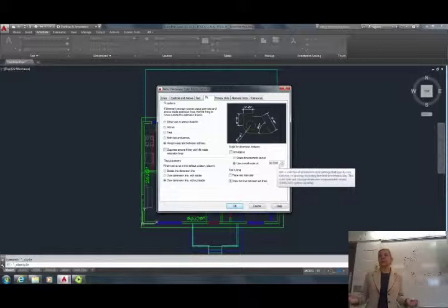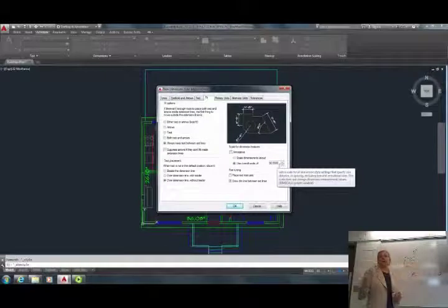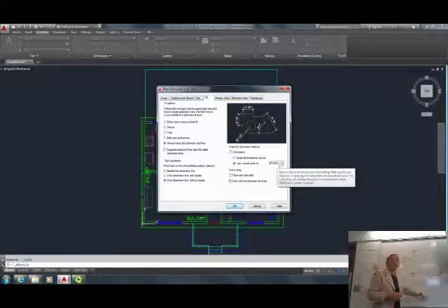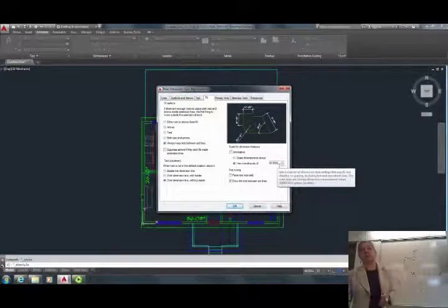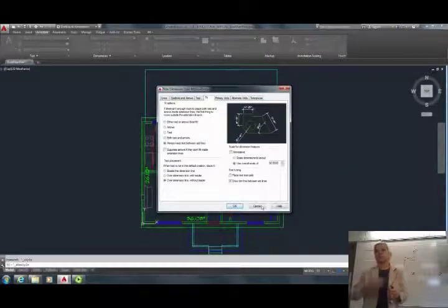I'm going to work with 100, 500, right? This is kind of like telling AutoCAD 1 to 96. You're going to actually find out that if you buy a metric template, you can use a 1 to 100 template for 1/8. You can use a 1 to 50 template for 1/4 inch scale, because they're actually very close. 96, that's a 4% difference. So it's kind of like saying 1 to 96. So that's why here in Imperial, we're saying 96. So if your scale is 1/4 inch, what would you say here? What's 4 times 12?